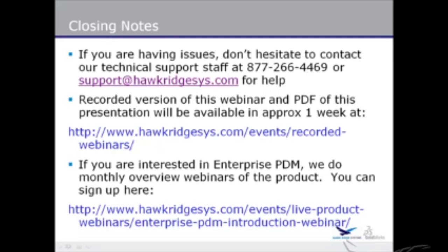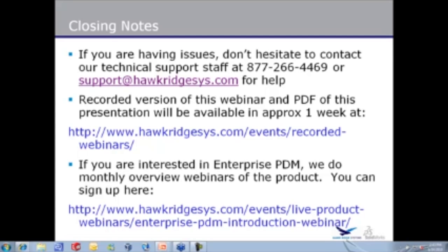Will there be issues running clients on 64-bit SOLIDWORKS and having the Workgroup PDM Vault on 32-bit? There will not be. You can have the Vault on 32-bit. You can have the Vault installed on a 64-bit computer if you want. It's just going to run in a 32-bit environment. So there's no problem running 64-bit SOLIDWORKS even though the Vault is 32-bit.